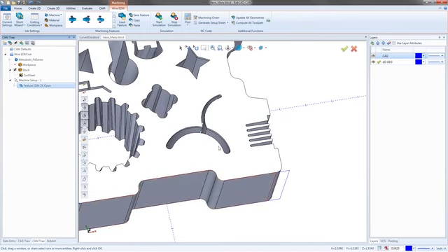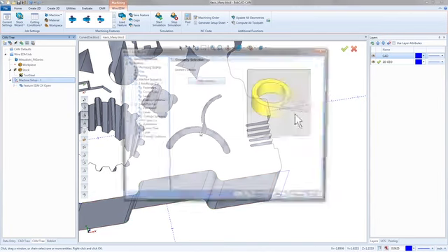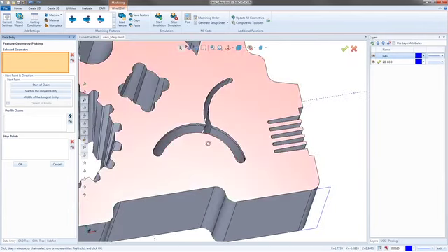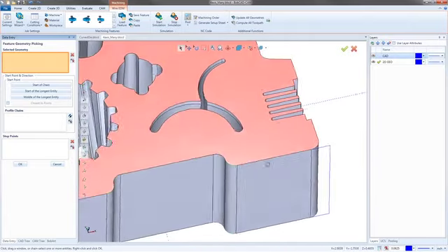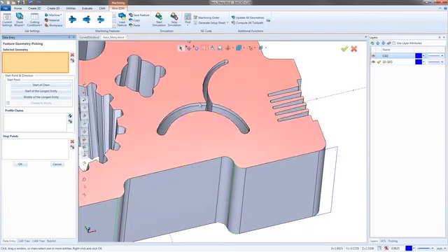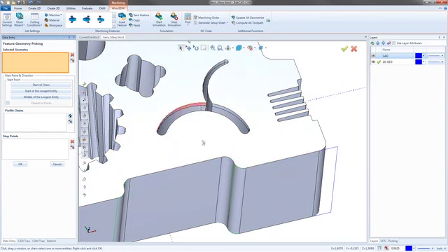So when I do these kind of parts, you can pick, because you're doing a 2-axis inside, we can go in and just say, I want to select the geometry, and I'm just going to pick the whole outside of this. Now, one trick to getting this, and this works anytime you're selecting geometry, like we're doing here, or boundaries. And that's a big one because you can use this for doing 3-axis milling with boundaries. But what you do is you hover over the edge. Don't click on it. You just hover over it and make it light up that pink or whatever color you use for your highlighting color.